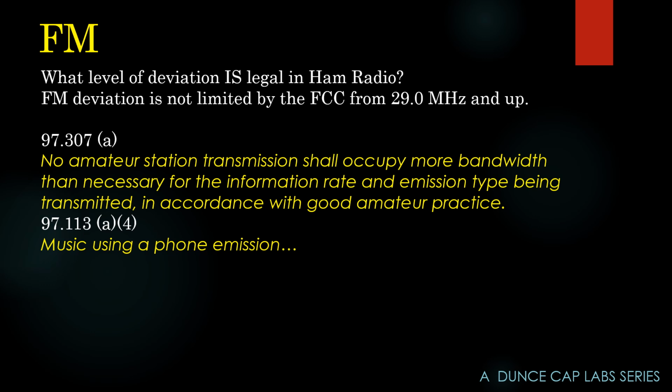Now, in general, we're not supposed to occupy more bandwidth than necessary. And of course, we don't send music and widebanded stuff like that over the air, right? So there are some limits, but they're not super specific. So on the UHF and VHF bands, you can get away with some rather wide FM for experimental purposes, but you wouldn't want to deploy a system of hundreds of radios like this. It would be very rude to your fellow ham operators to do that.